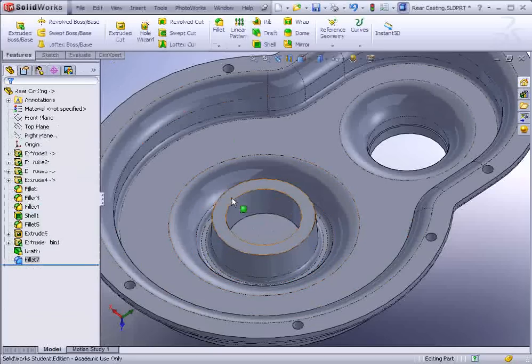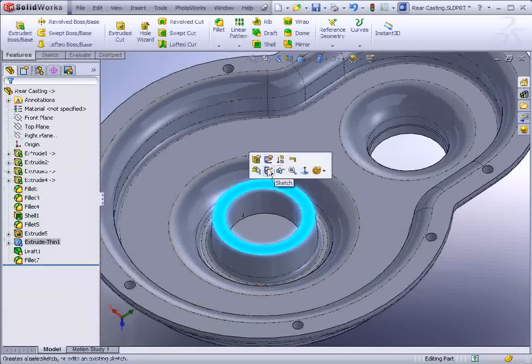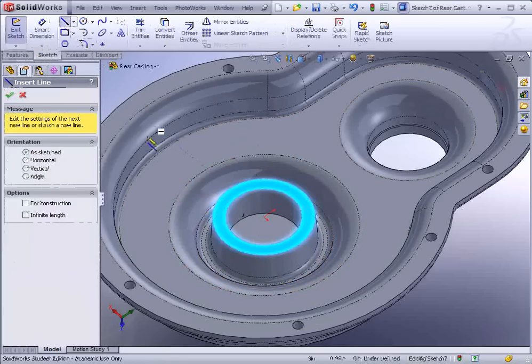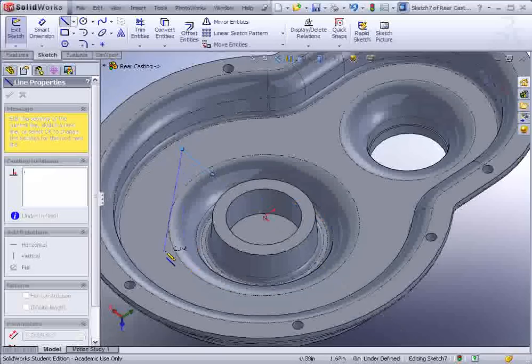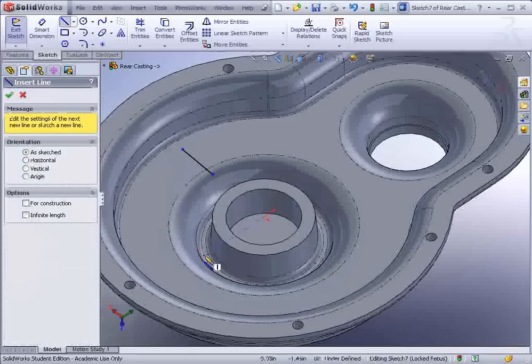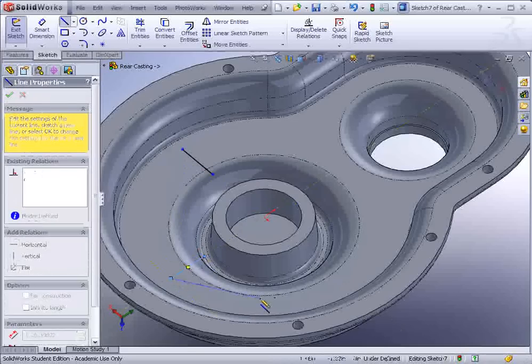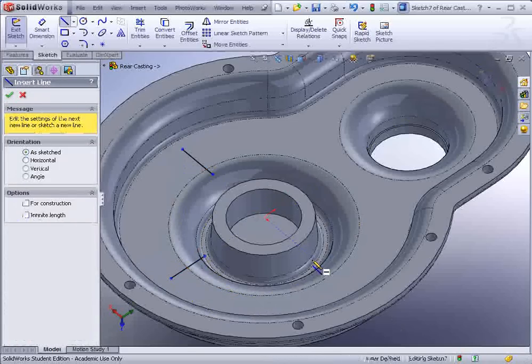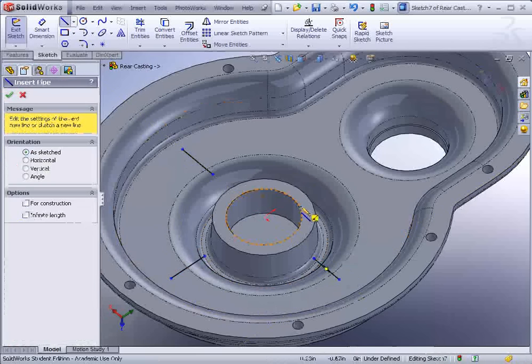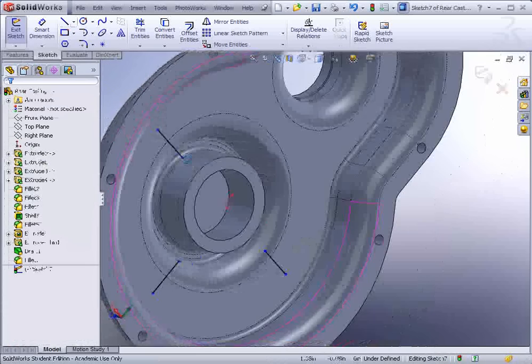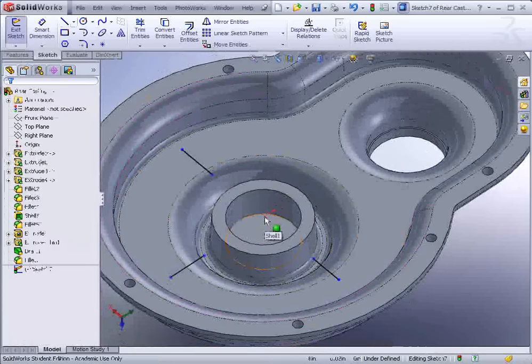Now we need to add the ribs. The ribs are created using the rib tool. Select this face, start a sketch, take the line tool, and find an alignment line yourself horizontally and vertically through the inference lines and just draw short little lines. Just like you see here, floating in space there. Now they are in alignment vertically and horizontally.